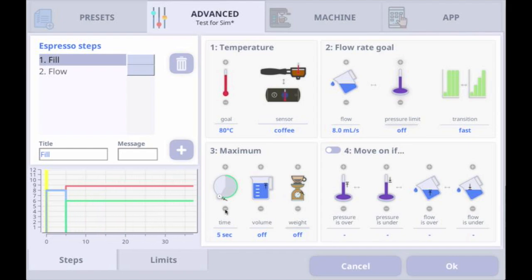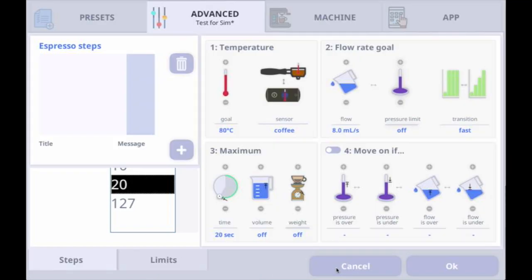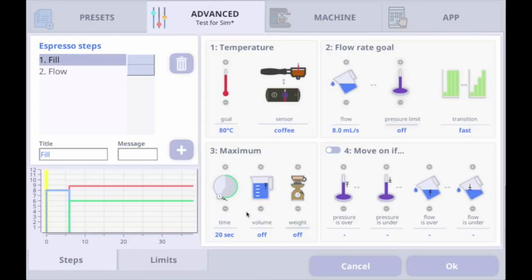At this time, if you adopted 3 seconds from another profile, you're going to have to increase that if you want to fill the basket before you move on. So even at 6 seconds, we're not going to be running long enough to fill that basket, assuming it is 50 mil space. So it'd be a couple of mils short there still. So the best thing to do is just set something that's going to be well above, so that time doesn't run out before we fill the basket. But we don't want to keep this running indefinitely, so we need some other trigger to monitor when that basket's full, and that's what we'll use this section for.